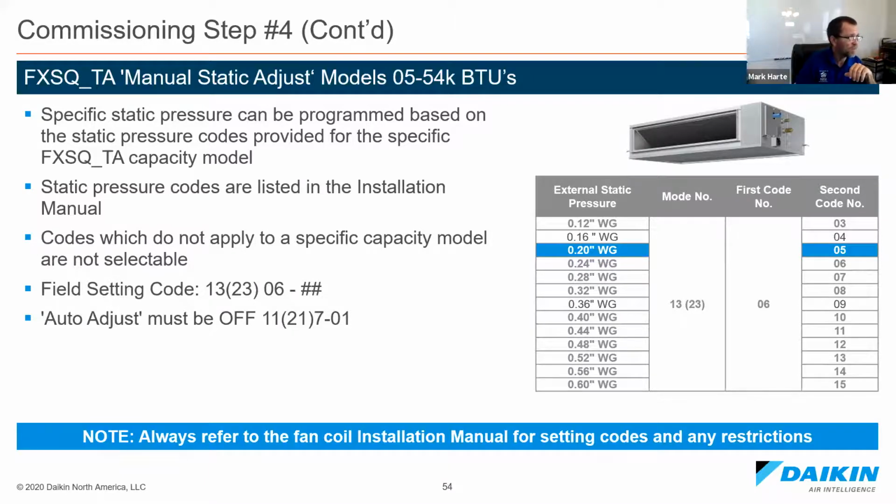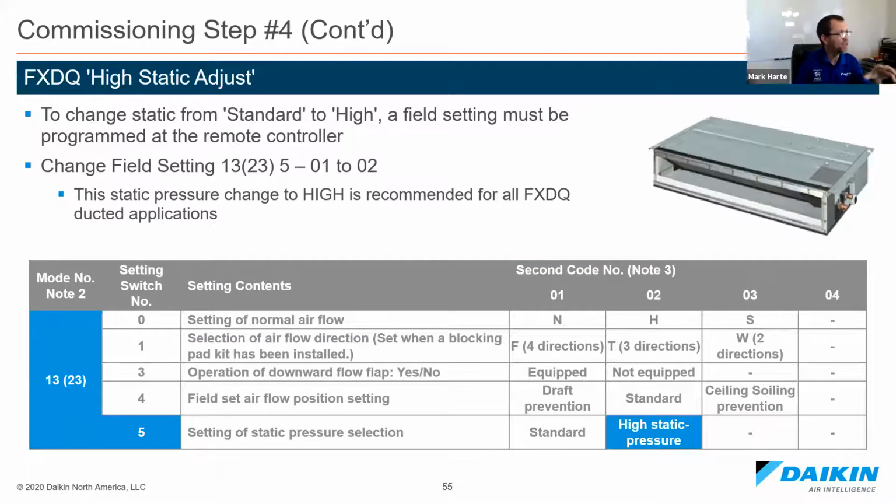So it's very possible. The FXDQ, this is the low static. You can go from standard, if you see in that bottom one there, setting a static from standard to high static.